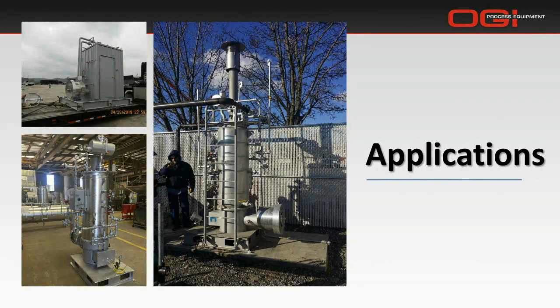And then finally, the last point would be it's a very quiet operation. Decibel levels 3 feet from this heater could be as low as 65. A conventional horizontal water bath heater would be 85 or higher, depending on your gas pressure to your burner. And so this is much quieter. So ideal for smaller stations with space constraints or stations where neighborhoods have noise limitations.